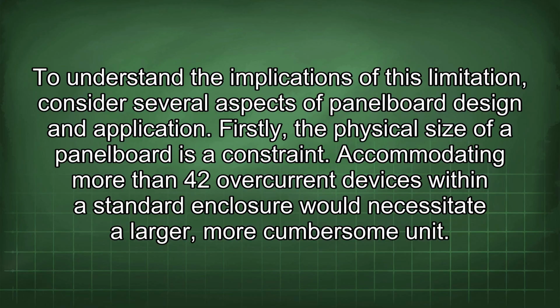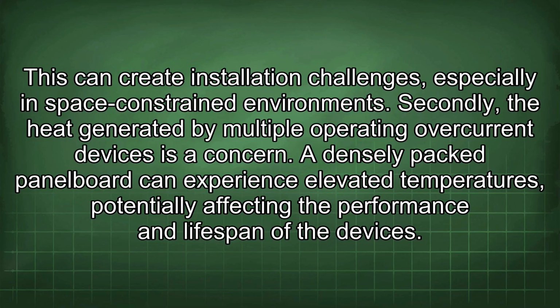Firstly, the physical size of a panel board is a constraint. Accommodating more than 42 overcurrent devices within a standard enclosure would necessitate a larger, more cumbersome unit. This can create installation challenges, especially in space-constrained environments.